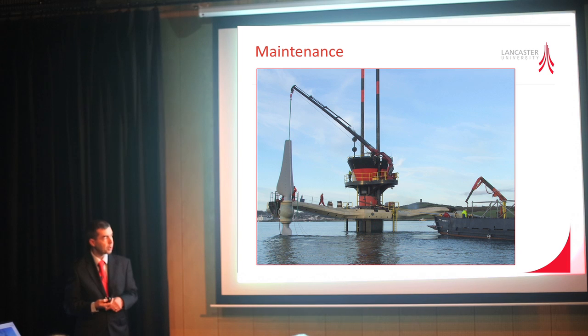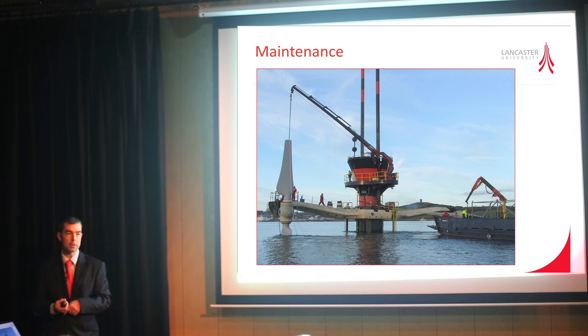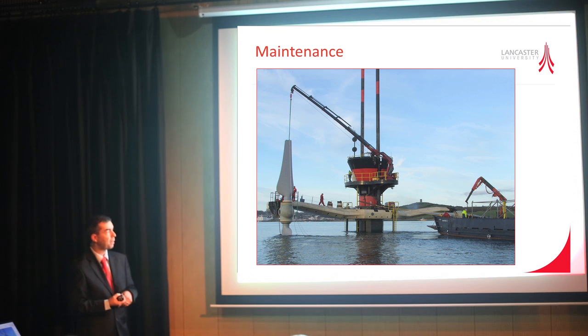Here's a picture of it undergoing maintenance. Maintenance of any tidal device is very important. Marine Current Turbines see their advantage as technically being that the blades are variable pitch, and the fact that they can twist them, so even if the water is flowing, they can pitch them to a 0 angle of attack, and therefore there's very little loading on it.